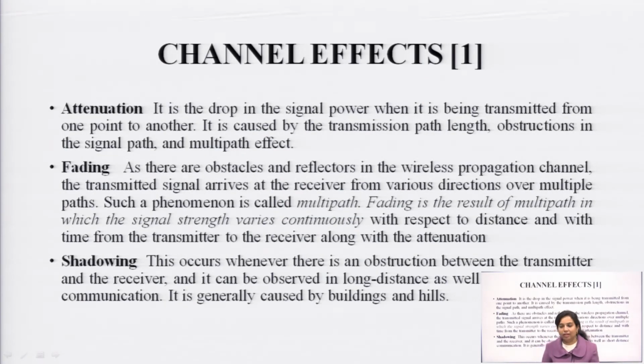Now, next is the channel effects. When we are modeling any channel, modeling means we have to derive an equation, we have to design a channel which is wireless in nature, which is unguided, and we have to design depending on different probability density functions like the Rayleigh probability density function or Rician distribution. These are the different probability density functions that we have to consider to design a particular channel.